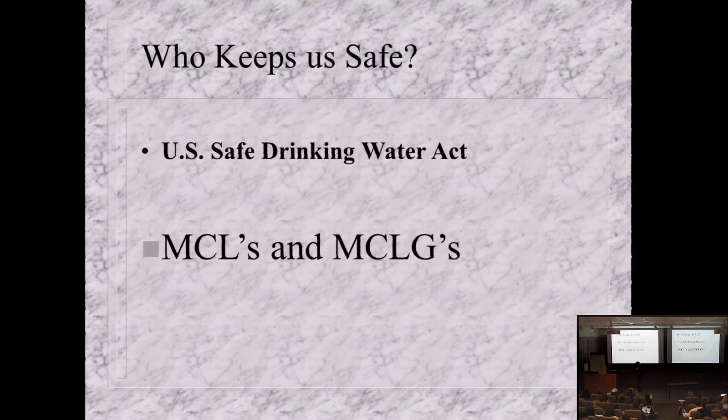If you're interested, you can go on the US EPA website, the drinking water tab, you can see what they test for and what the quality of water is everywhere. So drinking water out of taps is very, very clean. I told you that Boston water is super clean. The only problem, though, is that some old buildings, there was lead pipes and lead solder that was used to bring water to your tap. So some old buildings can have elevated levels of lead. It has nothing to do with the water supply. It has to do with your plumbing. To get around any chance of lead, all you have to do is turn the tap on until the water runs cold. Then you know it's coming from the road.